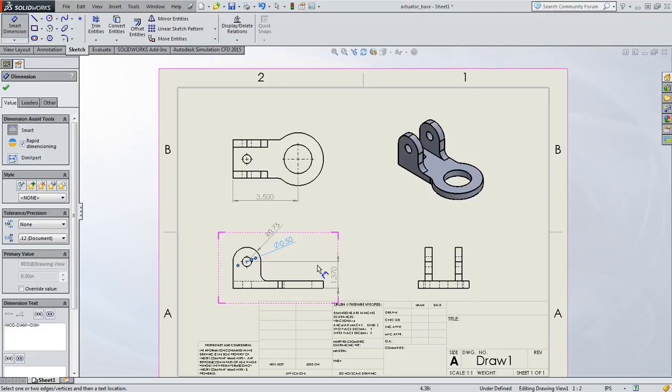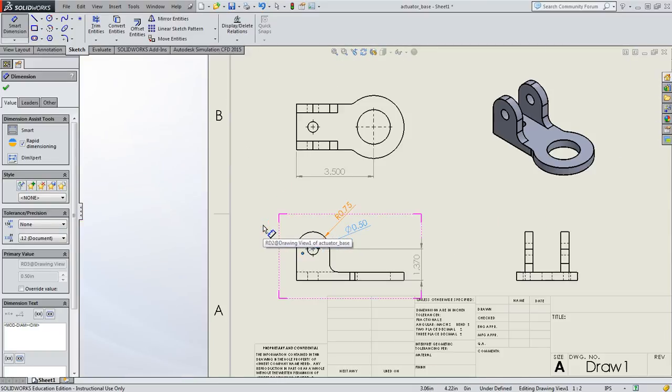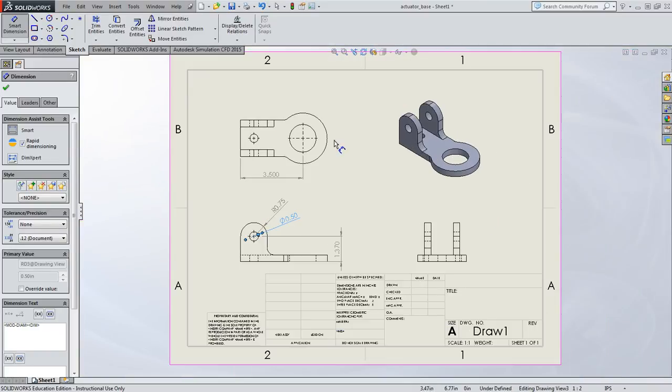If your drafting standard shows the numbers following the slope of the line, we are in what they call ISO drafting standards on an ANSI piece of paper, so our paper doesn't match the standard. We did this before.